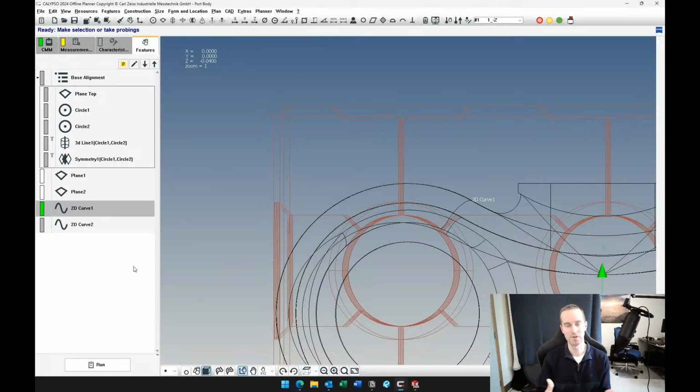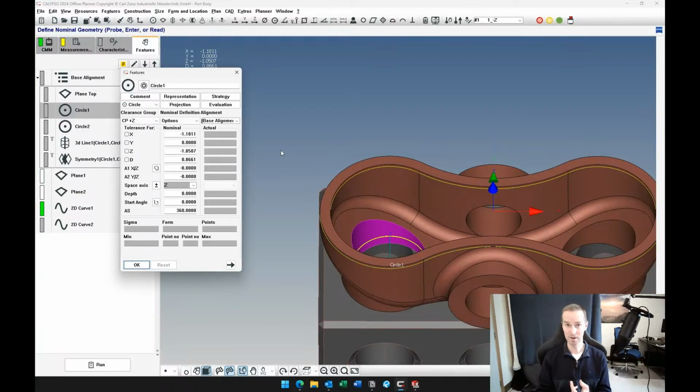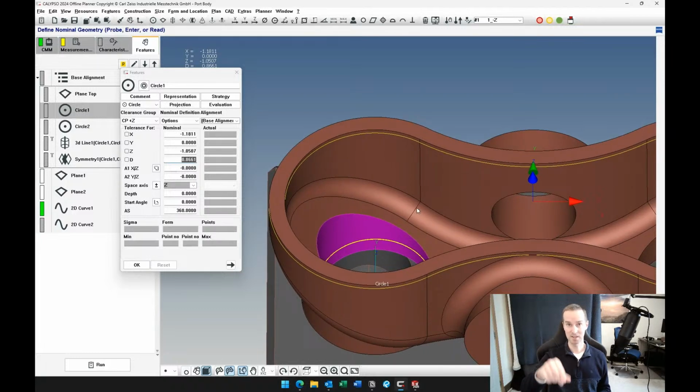Generally, when you're measuring a hole scan, which is very common, a good rule of thumb for the speed is the diameter. That's just what I use as a baseline, and then I adjust from there. The majority of holes you're going to be measuring are less than an inch in diameter. It also depends on the sensor you're using. The passive sensors are going to need to go slower than the active sensors.